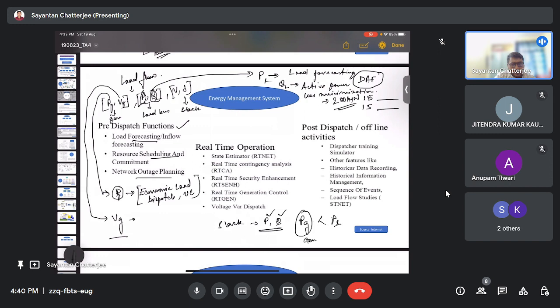If they violate the reactive power limit, because all the PV buses have reactive power limitations, then the bus would be considered as a PQ bus for the upcoming iterations. In each and every iteration the reactive power limit check is performed, and based on that we can switch between PV and PQ depending on whether the limit is within range or violated.